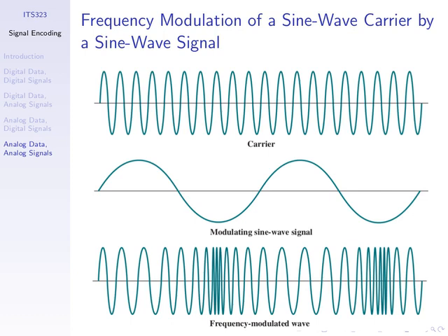This would be the input audio, the music or the voice. We'd have a carrier frequency. If your FM radio was using the channel 105.0 megahertz, that's the carrier frequency. And we change that frequency based upon the input. And that's what my wireless transmitter is doing. The carrier frequency is around 670 megahertz. As my voice changes, that frequency changes. As my voice amplitude is high, it changes the frequency of the carrier, and as it's low, it changes the frequency in the opposite direction. And this is what would be transmitted by my wireless transmitter to the receiver.